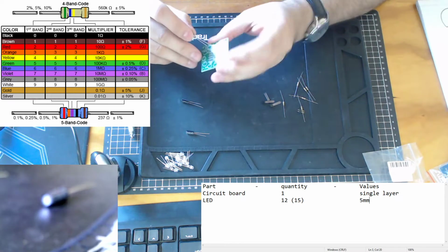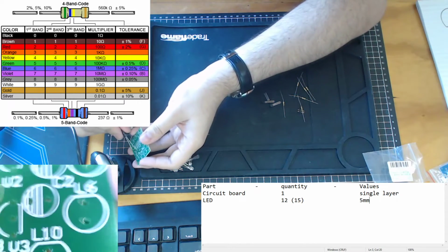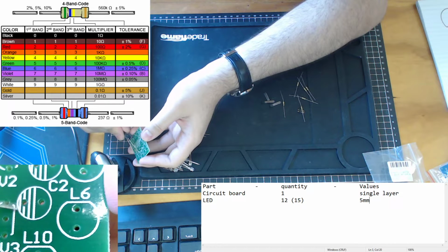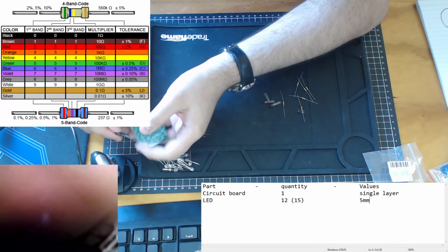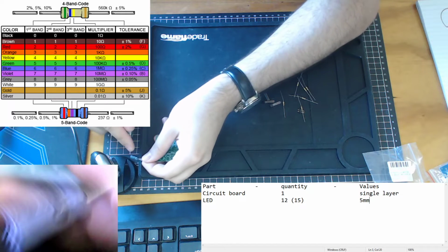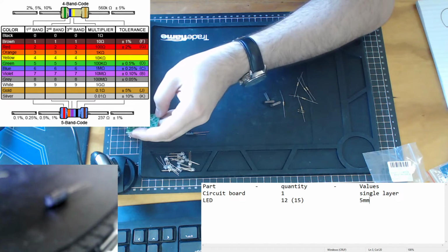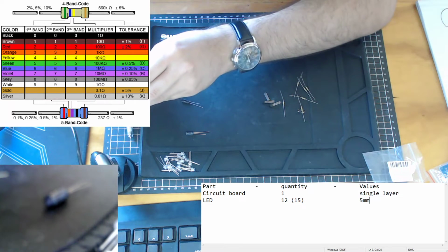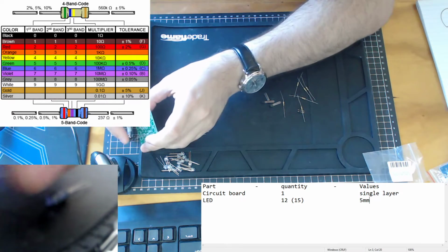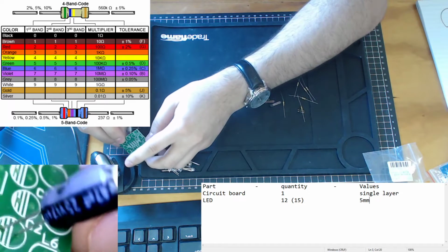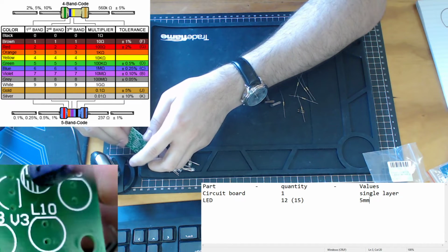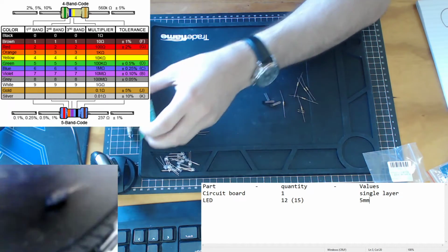And when we put that on our circuit diagram, if we look at the small camera over here, at our circuits, we see that we have some sort of white marking to the side. That white marking is going to relate to the white marking on our capacitors. So when we solder in our capacitors, we're going to have them in this way, and then we'll push that in. So we know that a capacitor is good.